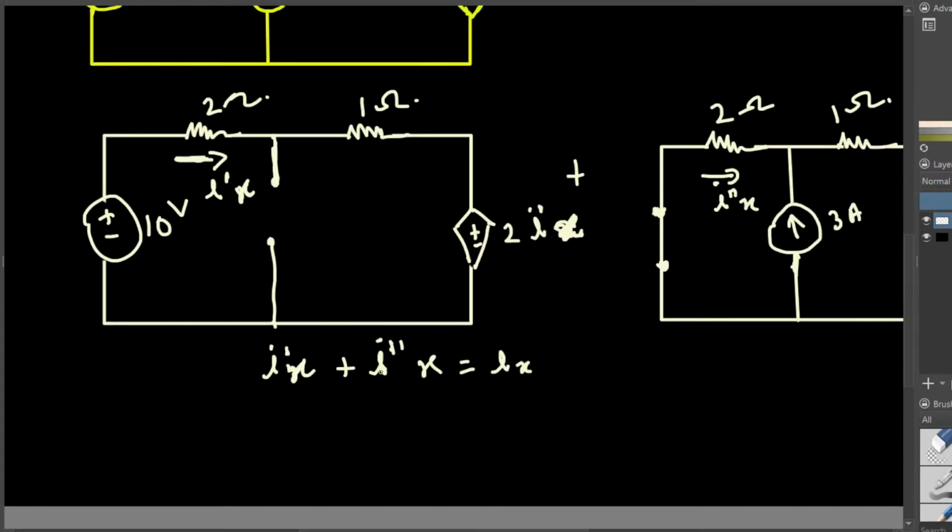So here we are interested in finding the current. For the first circuit right here, what is the best equation to use, KCL or KVL? You can see we don't have any node right here. This is a one loop circuit because this is an open circuit. When you have a one loop circuit, it's better to use KVL, because KVL says the addition of the voltages in a closed loop is equal to 0.